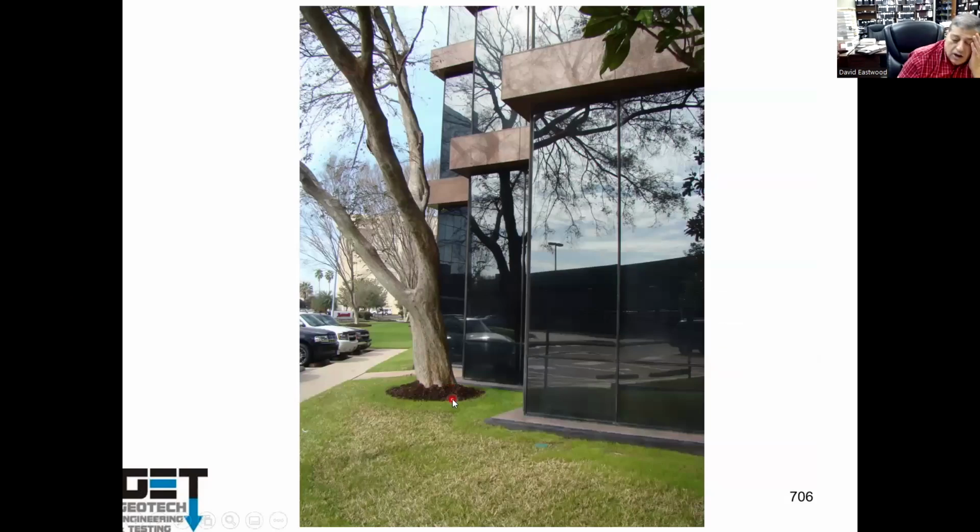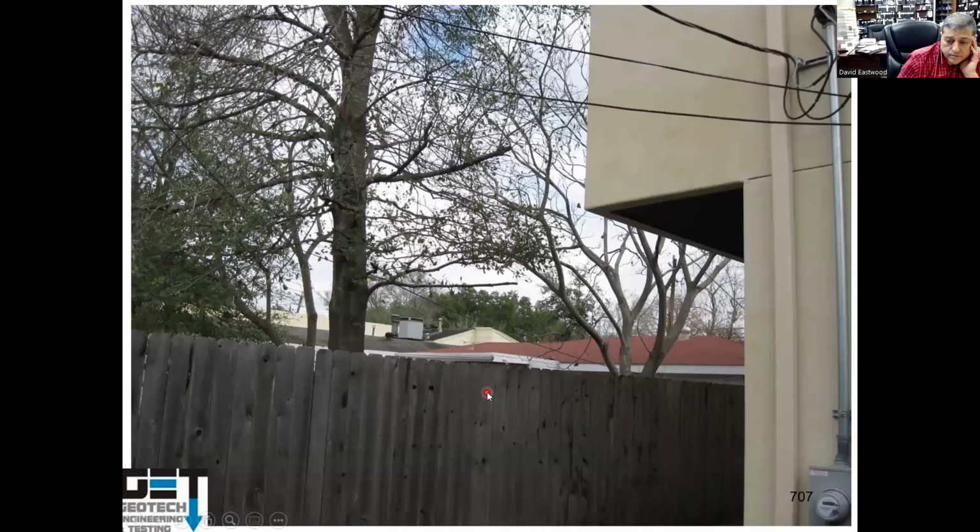Here's a tree next to this office building. If this tree died, this area is going to heave up, unless it was designed. Trees don't know anything about the fence. If your neighbor's tree dies, this building here is going to move up. So the structural engineer should know about the presence of trees and trees dying. You got to design a structure assuming this tree is going to die one day.